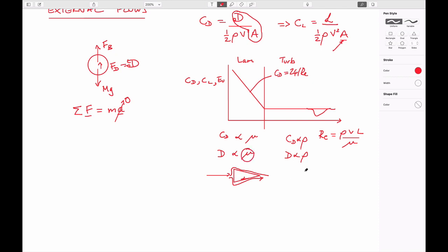If you're in this regime here, then typically, just as in the case of the truck being dragged behind the aircraft, the stagnation on this boundary is the bulk of the force that's applied, and that's proportional to the momentum that is destroyed on that face, which is proportional to density.